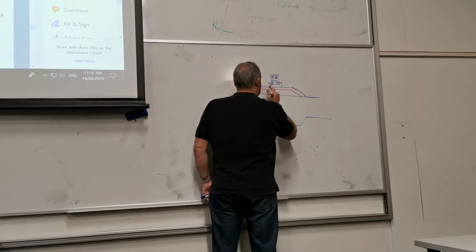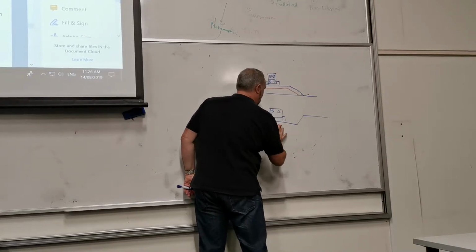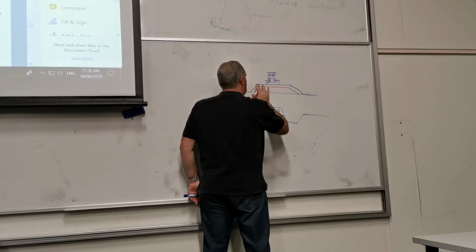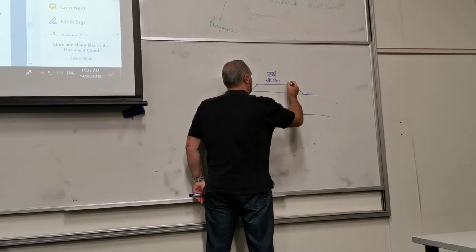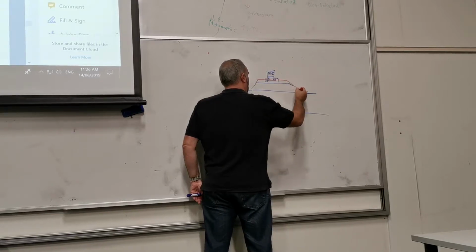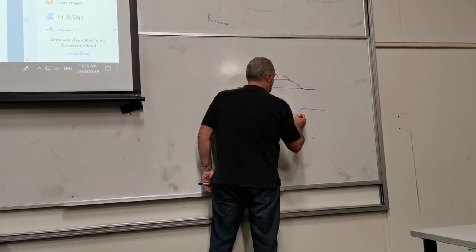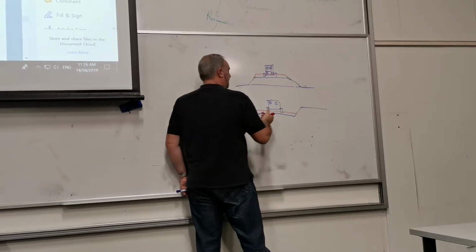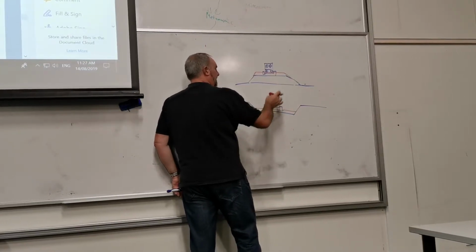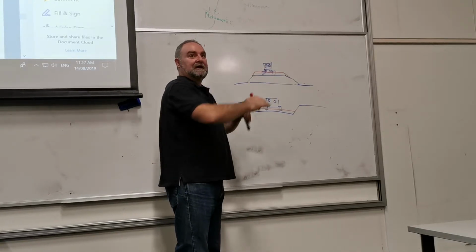So when you drop the level of the road down, sorry, did I say cut? Less cut, you raise the road. You raise it in fill, and obviously it would be raised here as well. So we have less cut and we have more fill. So therefore the balance comes back to zero again.